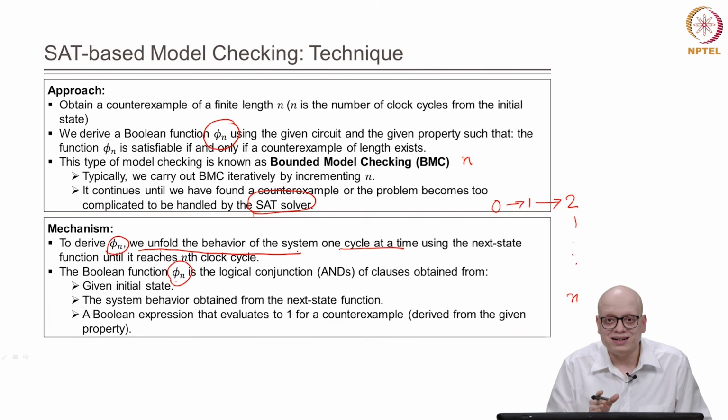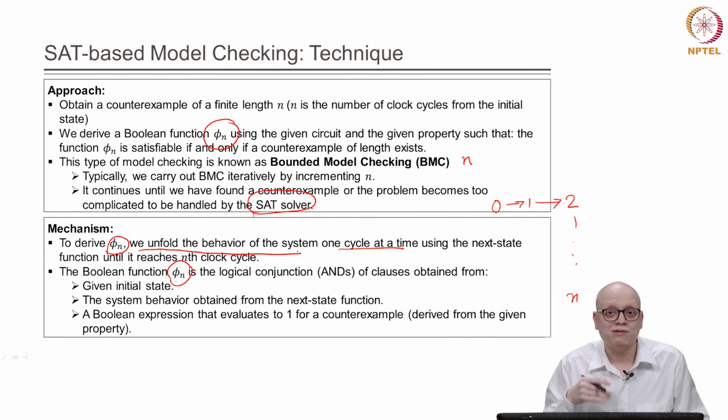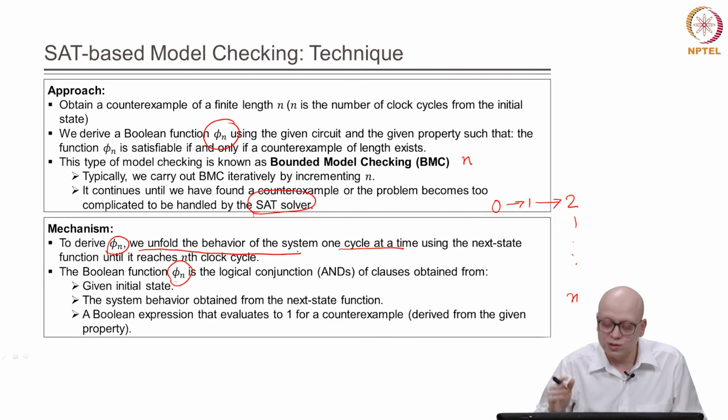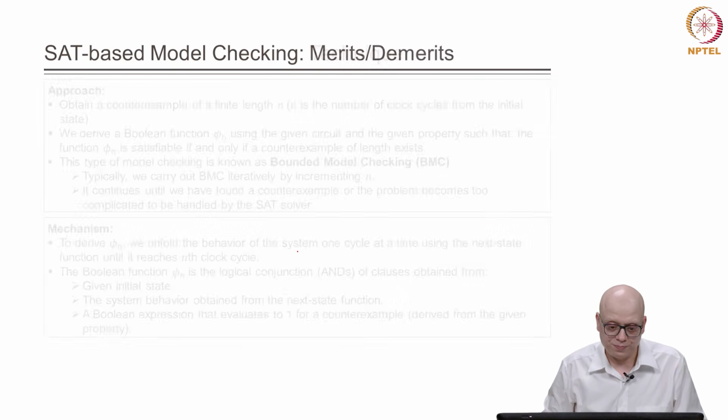In that sense, it is still a formal verification technique, because it is not taking a sequence of inputs from the designer. It is considering all inputs, the entire input space, but it is only unfolding up to n clock cycles, and therefore, in that sense it is incomplete.